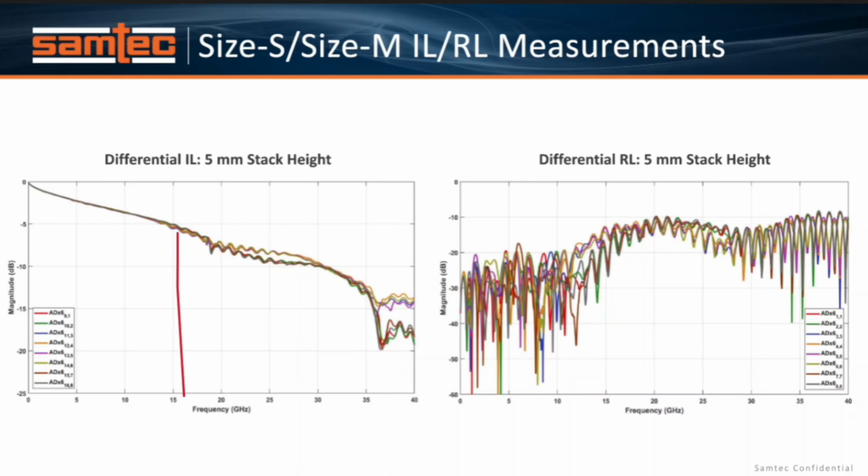Given that the overall channel loss of PCI Express 5 is 36 dB, the mated connector set in the breakout region only has 6 or 7 dB of loss. So that gives you an additional 30 dB of channel loss where you can route signals across the system.